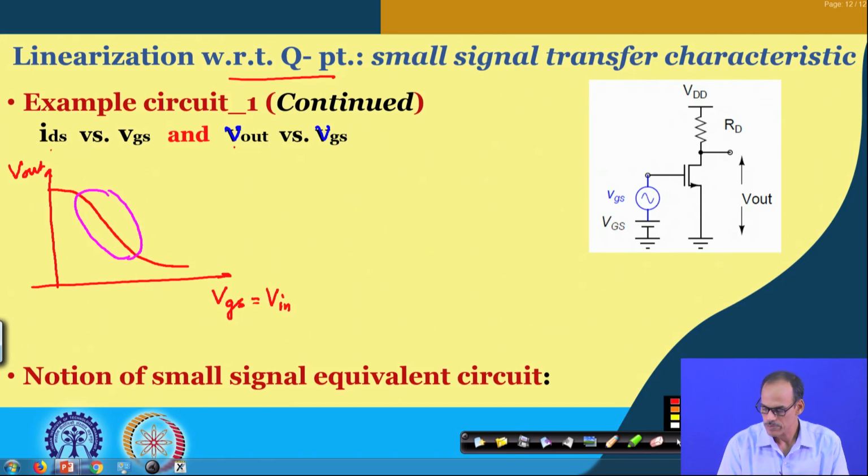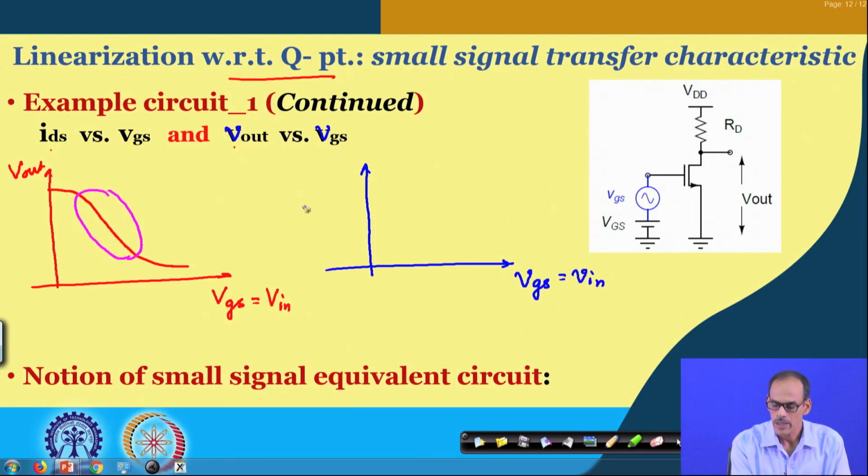Once you pull it out, and if we observe the corresponding transfer characteristic, its x axis is small v g s, or you may say small v in, and then the y axis is v out, which is actually small v d s, and this part is coming here. If we extend, of course, it will have a nonlinear part.